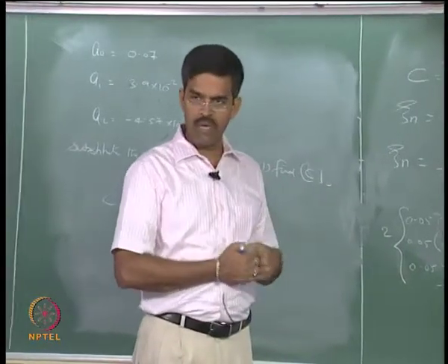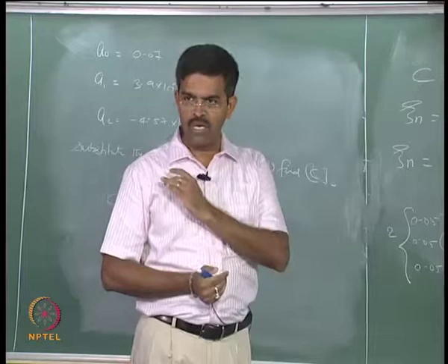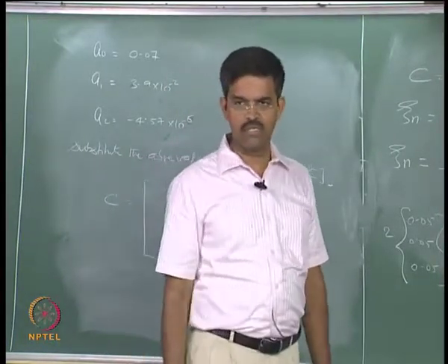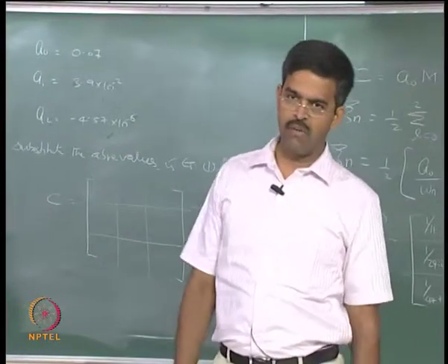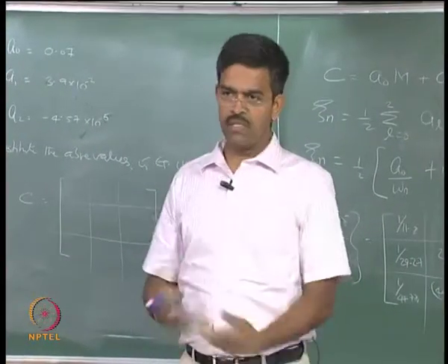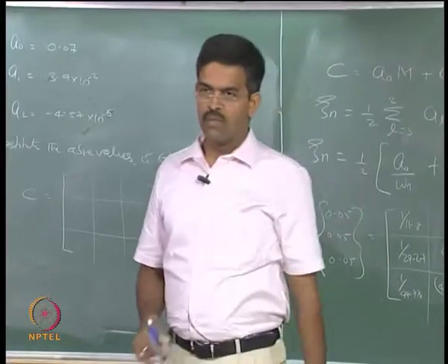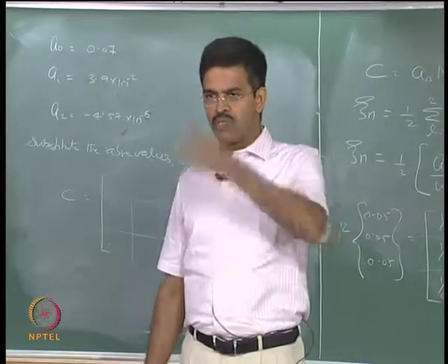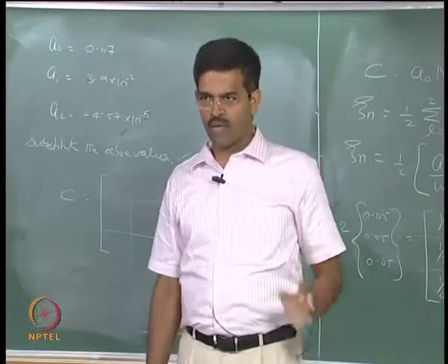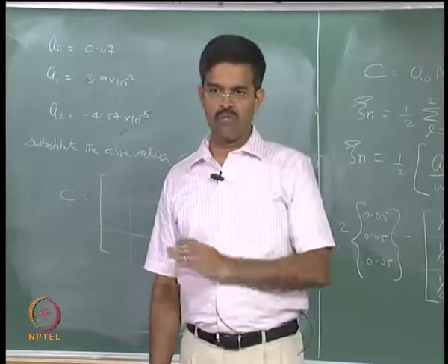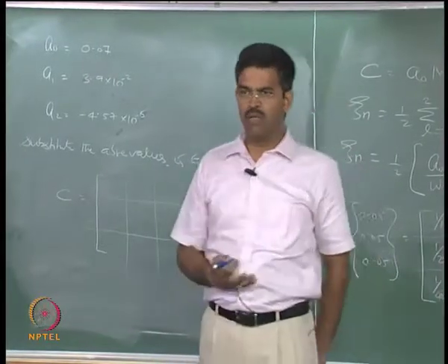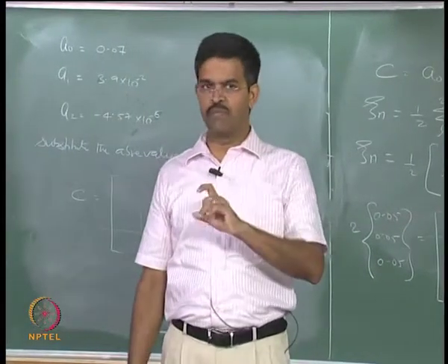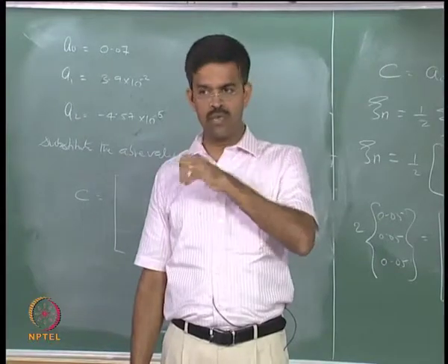Once we discuss that in Monday's lecture, then we can come back to the original TLP problem. We have got M, we have got K, we have got f of t, understood. Now, we will show how we have got C, then we will run the analysis using a specific iteration scheme because it is an iterative process, get the results and discuss them quickly from a paper. That is how we will complete the discussions on TLP and how f of t handles different kinds of forces like wave force, current force, earthquake force, stability forces, how it is modeled and how it is taken care of in the dynamic analysis. We will address that f of t part separately. So, that ends the discussion on TLPs.